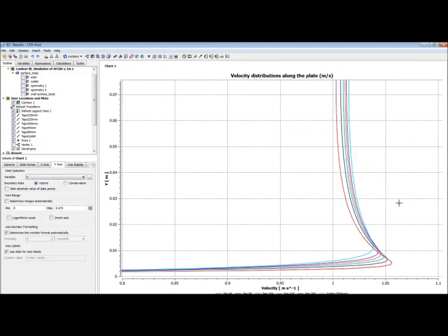This is starting to look a bit more like the boundary layer velocity profiles you're used to. What we haven't plotted on here is the Blasius solution, but then we would need a normalized velocity. Now, luckily, the normalized velocity here is identical to the velocity, because our velocity in the inlet is 1. So what we have got is a slight development in.